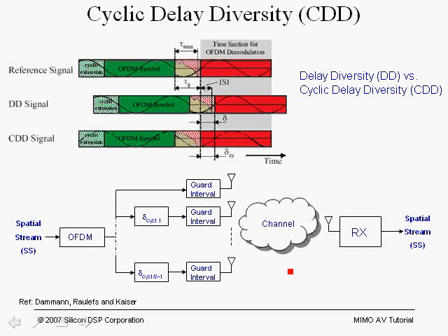This is one of the big reasons why CDD was adopted by the 802.11n draft, because it provides transmit diversity. We have the fact that all transmit antennas are active. It improves the range by adding diversity during the processing of the preamble, and does not break the legacy 802.11a systems that may coexist with the 11n system.